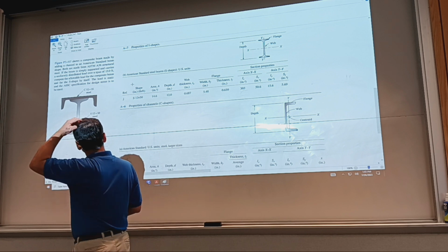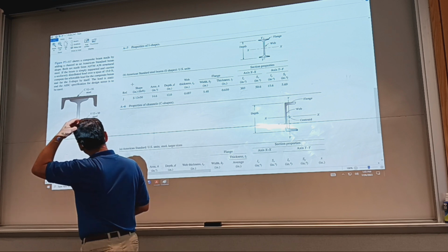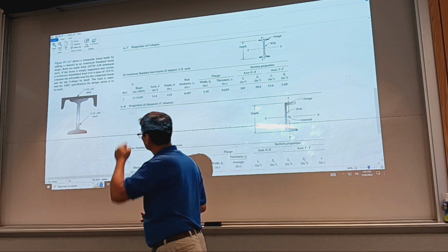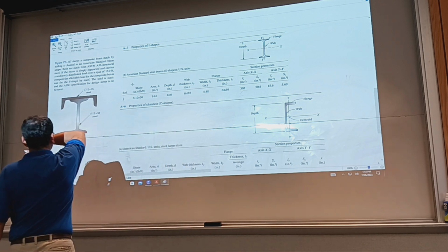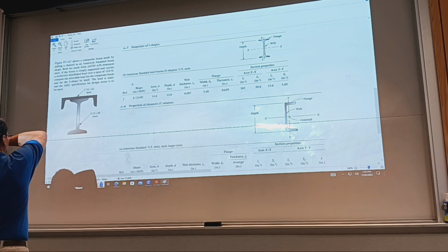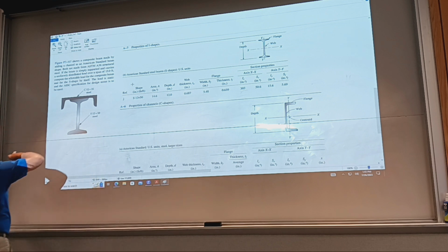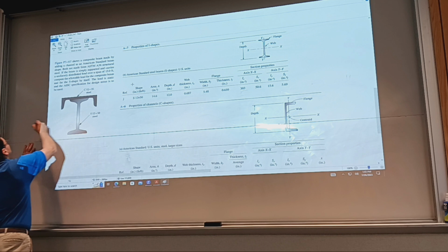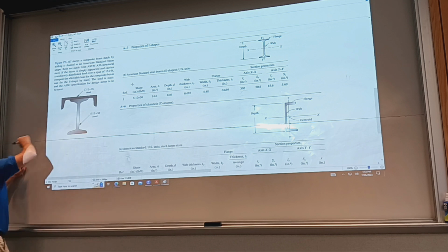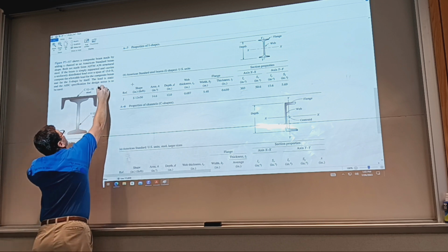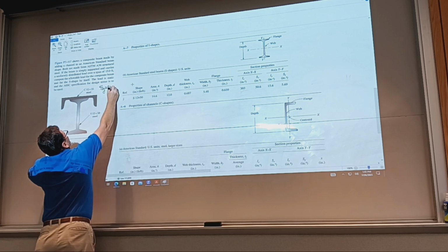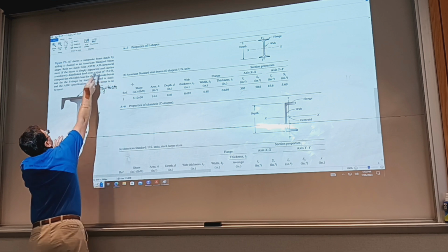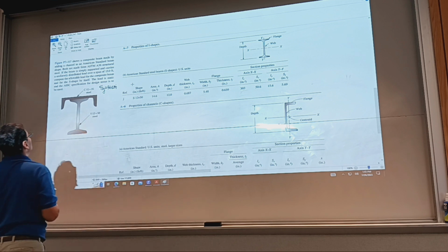The load is static and the American Institute of Steel Construction specification for design standards is to be used. So we have the material ASTM for both. The Sy for both is going to be 36 ksi. It's part of the name, ASTM A36.